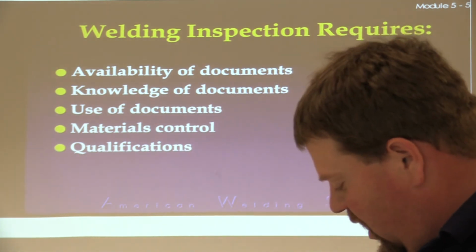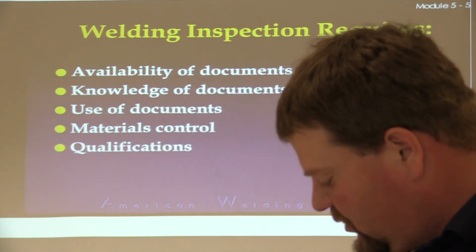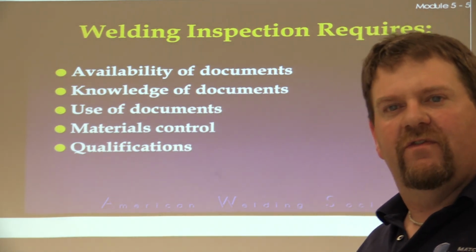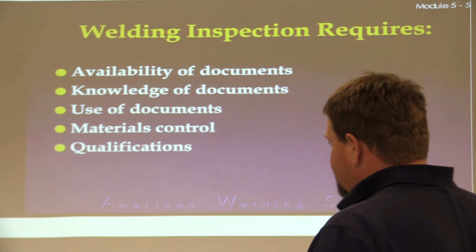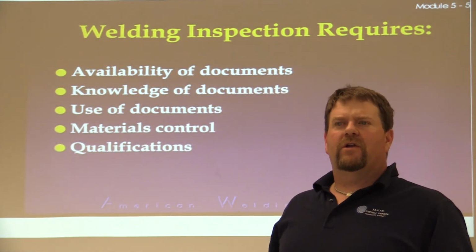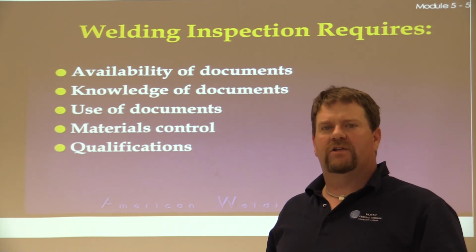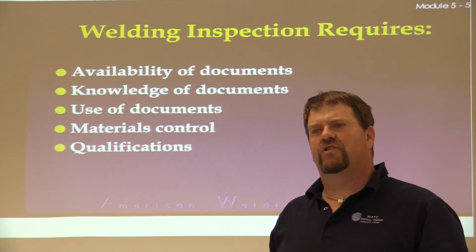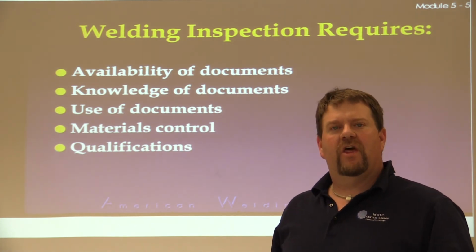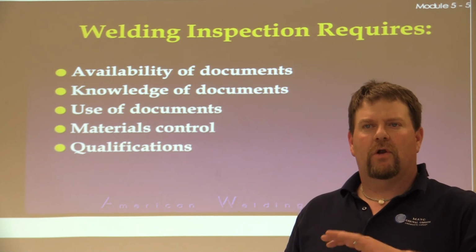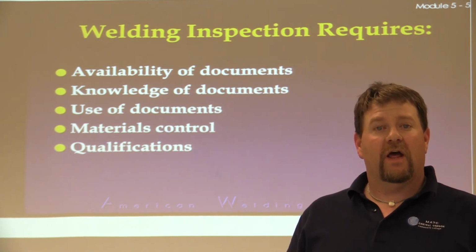Right-hand column talks about, it says, once qualified, the welder will be permitted to weld in production as long as that welding does not involve position, thickness, electrodes, etc., which are outside the limits of the qualification. So it's kind of like the essential variables, right? As long as the essential variables are the same, then we're good to go. So say you work at one company and you do these 5G welds for a long time, or you mainly only do 5G welds, same electrodes, same positions. You qualify within them, and what AWS is saying here is they accept you to be qualified as long as you go, unless you start proving otherwise.